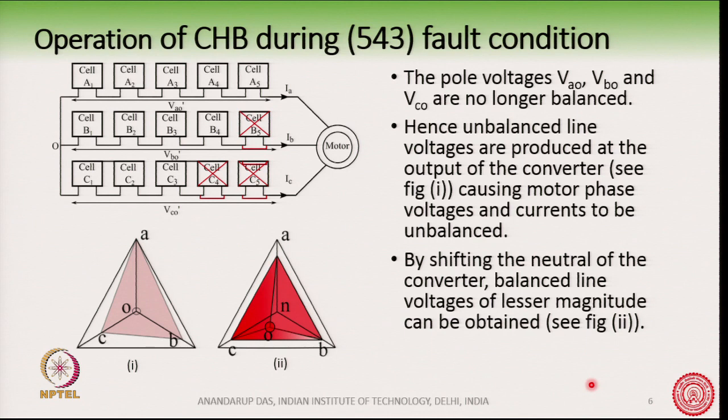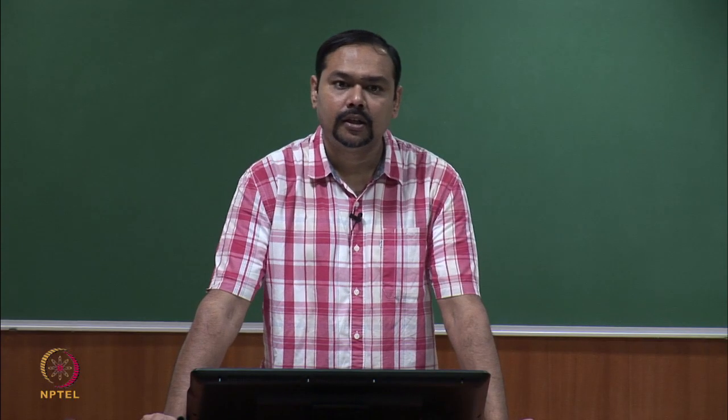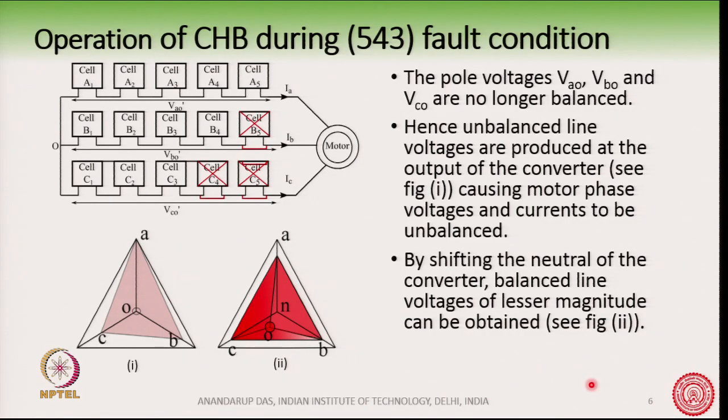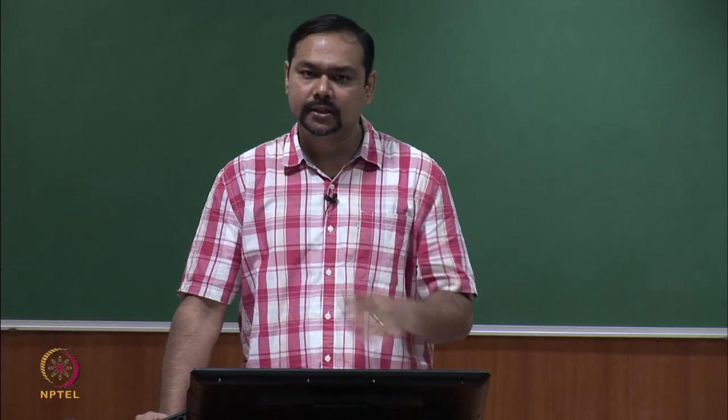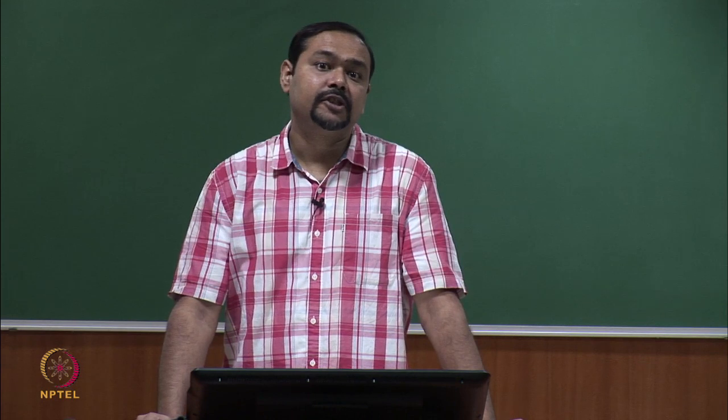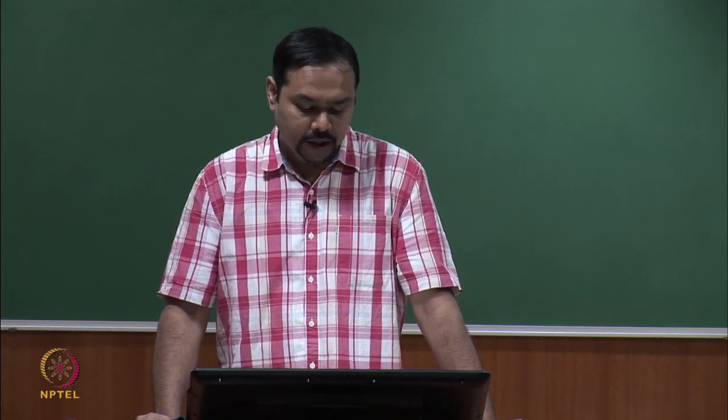Compromising on this safety factor is actually not a good idea. We must keep this safety factor, otherwise if you increase the DC bus of these cells, it may happen that you lose all the cells over a quick time, because you have compromised on the voltage safety factor. That you do not want. You do not want to compromise on the safety factor which has been kept there by design. So, increasing the DC bus voltage on these cells is not a good option.